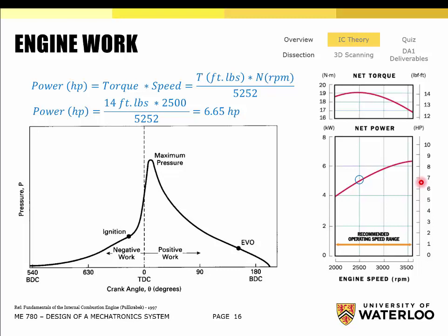However, what happens if we change down a gear? We're now going to operate the engine at a slightly higher engine speed, but we have more mechanical advantage in terms of the gear ratio, because we might be operating the engine at a certain speed, say 2,000 revolutions per minute, but the wheels are not traveling 2,000 revolutions per minute. They're slower than that. So we can change down the gear just like you do on a bicycle when you start climbing a hill, because you need more torque to climb the hill. Once you reach flat ground, then you can go up a gear so that the engine speed can go lower. Hopefully that makes sense.